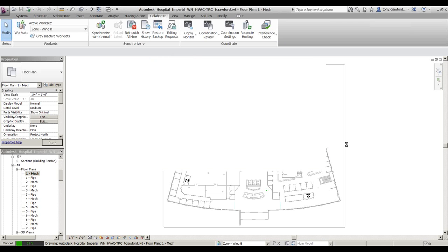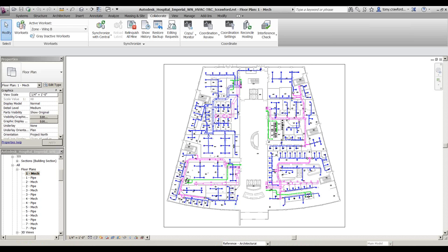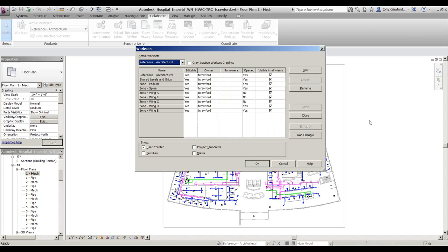So if I was working on lighting, I might close all of the mechanical and all the plumbing. If I was working on furniture, I'll close the lighting and the plumbing. And the difference this makes, instead of just turning it off in the view, is that it's global, it's the whole project. It's not thinking of it at all. It's not just hiding it in the view. That does help that one view, but it's not doing any great significant value for Revit. Well, that answers the question, because a lot of people spend a lot of time linking in files and doing it correctly, and we wanted to make sure they weren't thinking, oh my gosh, all this work's just going to disappear now.